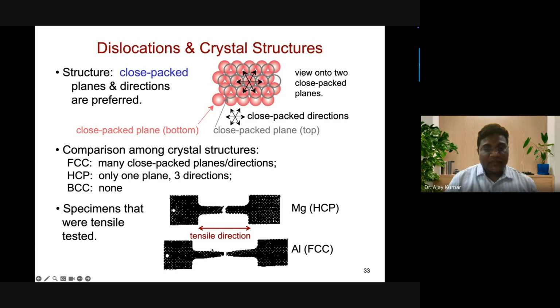So you have to basically prepare the sample. This is the dog bone specimen. Then you have the gauge length, right? And in between the gauge length, this will go to the grip of the machine, right? We have top and bottom overheads. Then you apply the tensile load. We have the load cell.